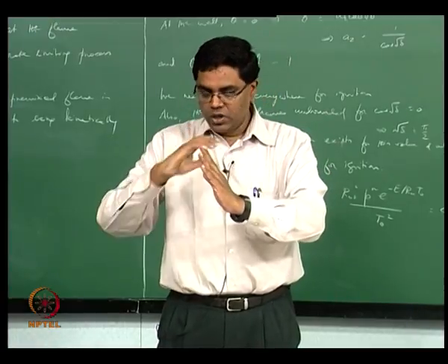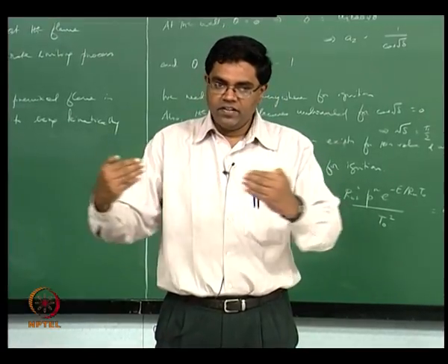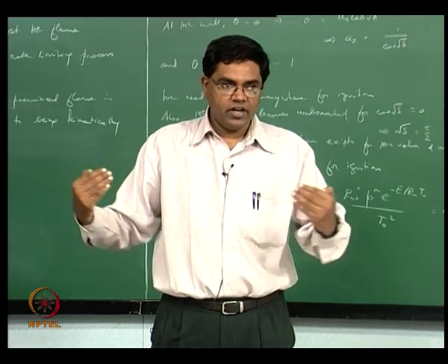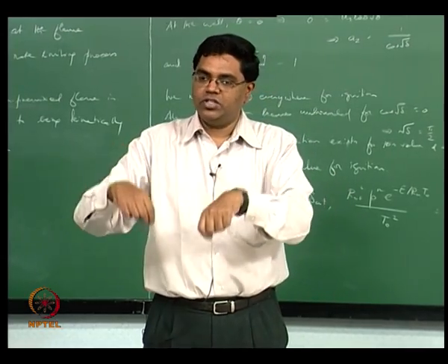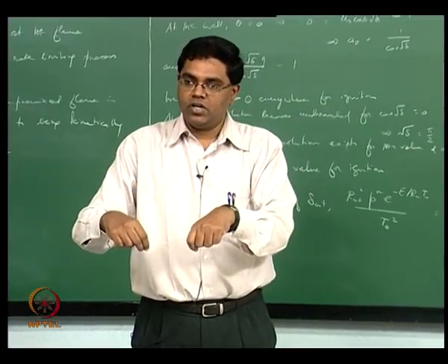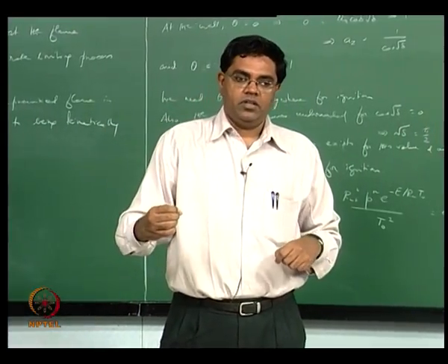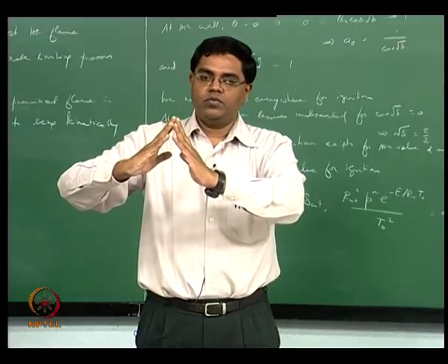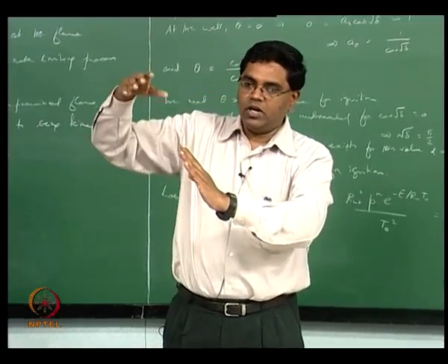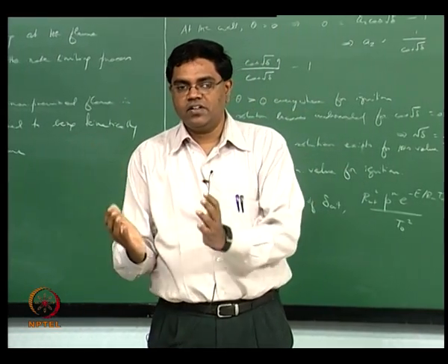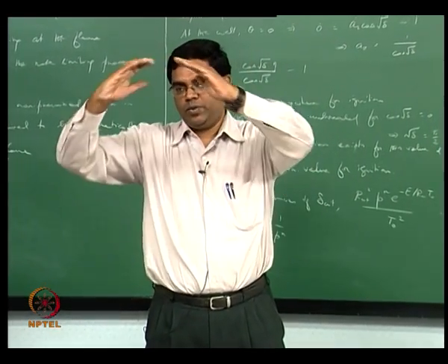One, as the air entrains at the base of the flame, you are going to have an enrichment of this mixture, and it's going to be closer to stoichiometric and actually get anchored much more firmly. The other thing is, for the remaining shoulder of the flame, you're going to have fuel rich products that are coming out, and that is going to mix with the reactants and have a diffusion flame envelope, right.